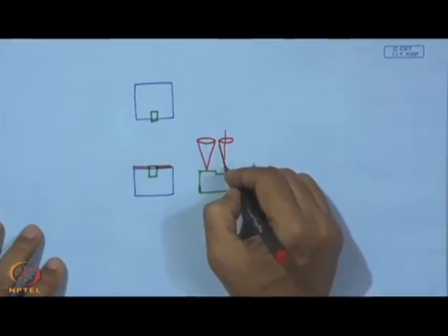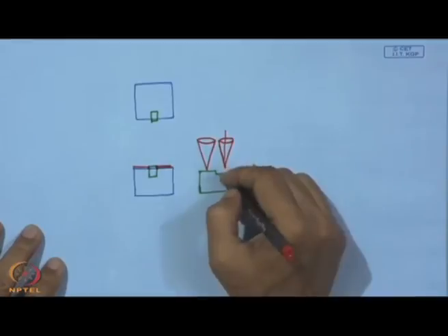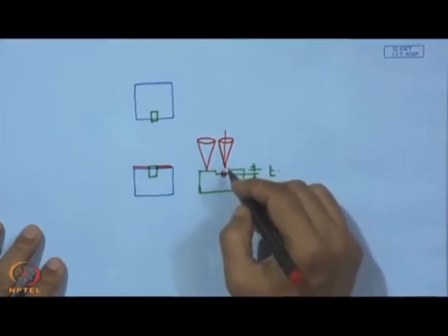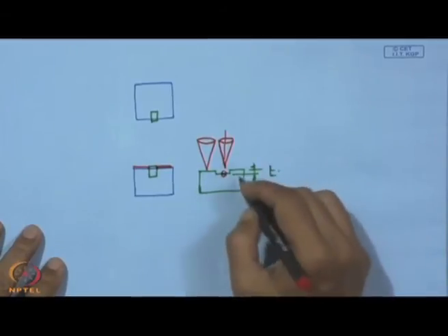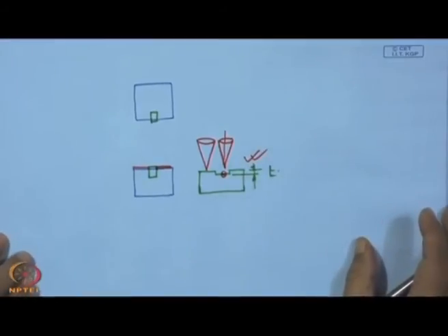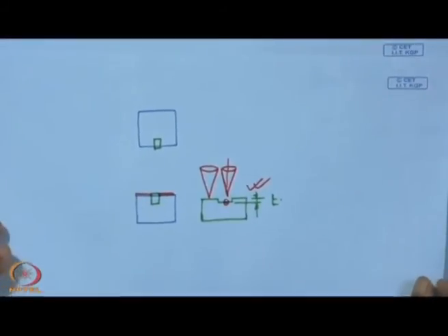So, this is the point here, and then we can lower the lens of this microscope, transferring the focal point to this surface, and from that it is also possible to assess the thickness of the coating. So, this is either by masking, by using a Talystep, or by using this depth focusing lens.